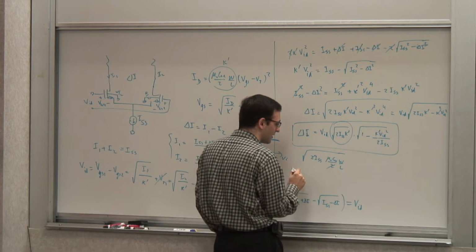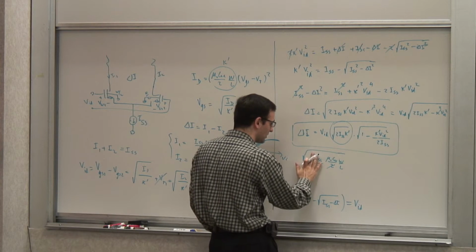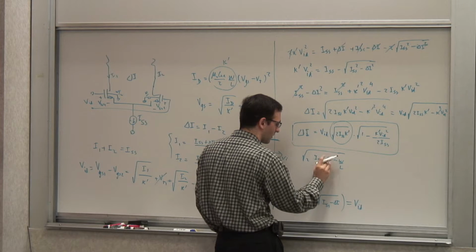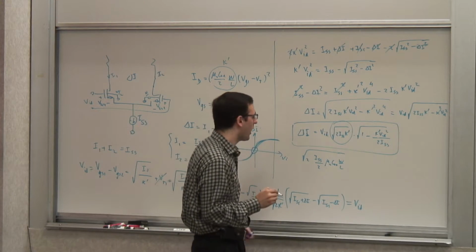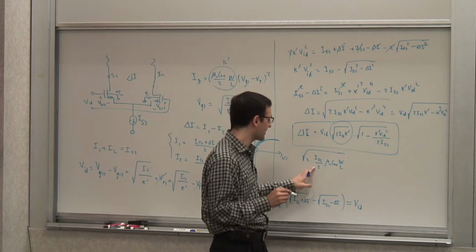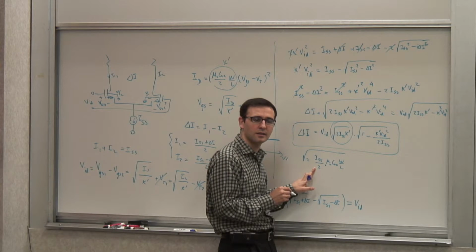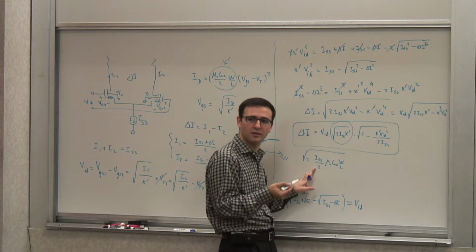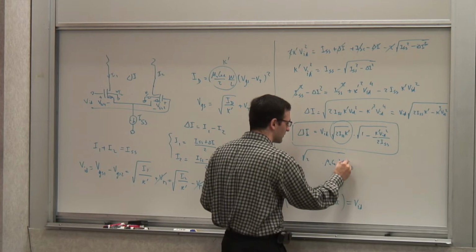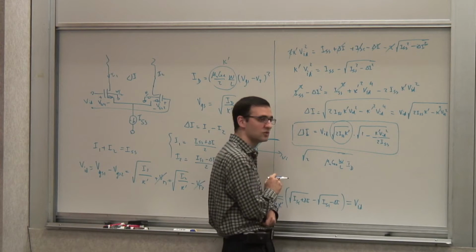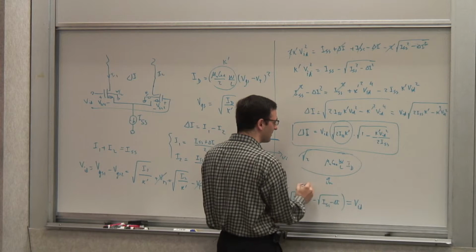Well, let me rewrite it in a slightly different way. So now I can divide it by ISS and then multiply by 2. So let's get rid of these 2. What is 2 times mu n C ox W over L ISS over 2? What is ISS over 2, by the way? It's the drain current of each transistor, right? So it's ID. What is this quantity? GM. So for small perturbation around here, this is simply GM VID.